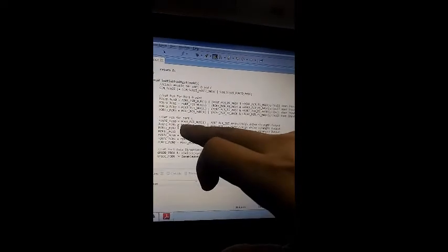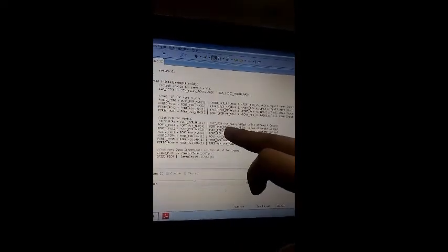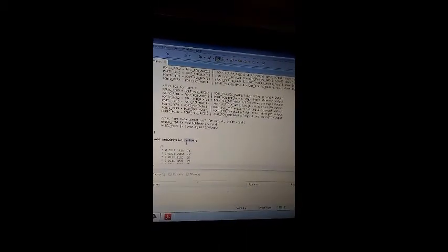For the initialization part of our function, first we enable port D and port C, and then we set PCR for the port D pins, which we pull down because it is active high. Then we set PCR for port C for the segments, which light up the LED 7 segment. Then we set the port data direction, 1 for output, 0 for input. This is input, 7 segment is output. Next, we pass to the next part of the code.